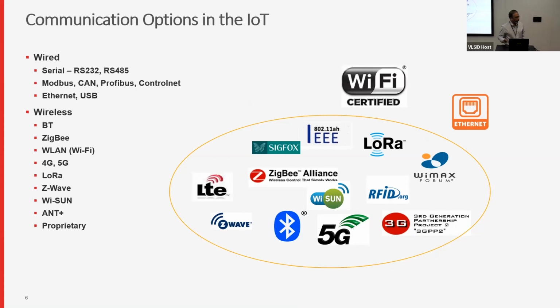Every particular application differs: whether it's short range, long range, small data, more data, what kind of network it is, star network, whether the license is paid for or free. All IoT works on license-free spectrum. Licensed spectrum like 4G, 5G is very expensive. So once you're paying a heavy amount of money for a piece of spectrum, 1 megahertz or 10 megahertz, your entire protocol becomes bandwidth efficient. So the way the protocol is defined is different for licensed spectrum versus unlicensed spectrum.